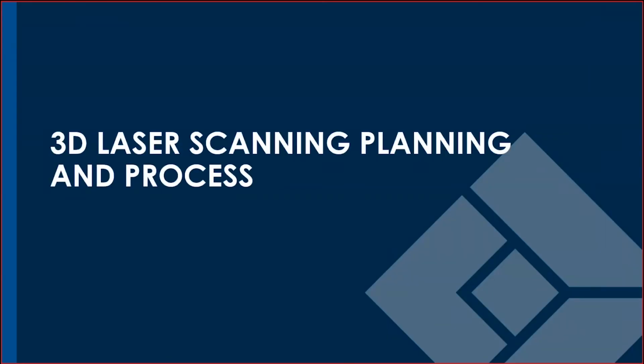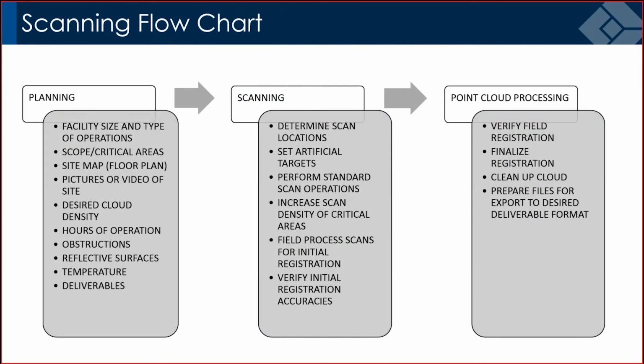Okay, so now what I'm going to get into here is considerations for scanning, how our operation works, and how to get something from point A to point C, actually primarily point A to point B. When we look at scanning, one of the first things we need to look at is planning. It's an important part of our scanning operations because the more prepared our teams are prior to showing up in the field, the more efficient they can be. Items such as floor plans, pictures, videos, anything that helps us understand the actual site before we get out there is going to be super helpful.